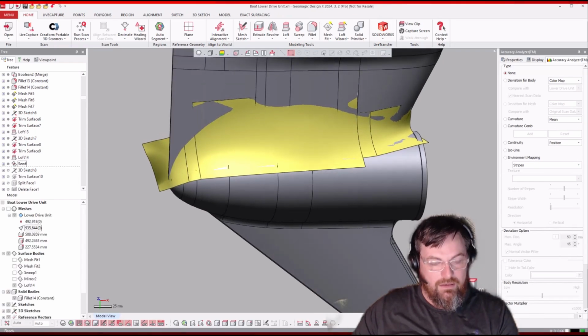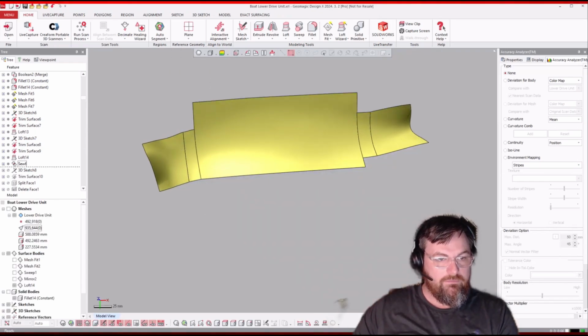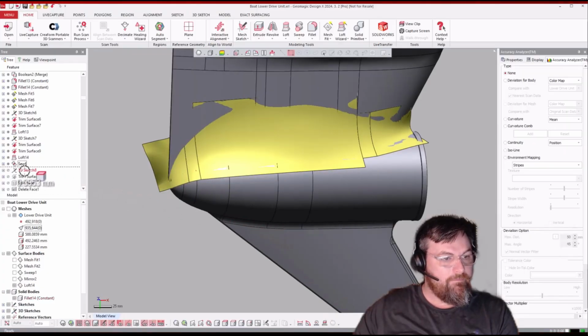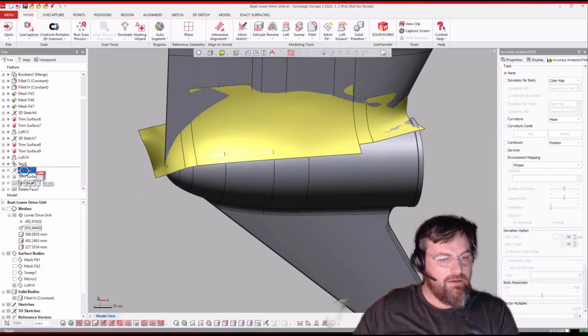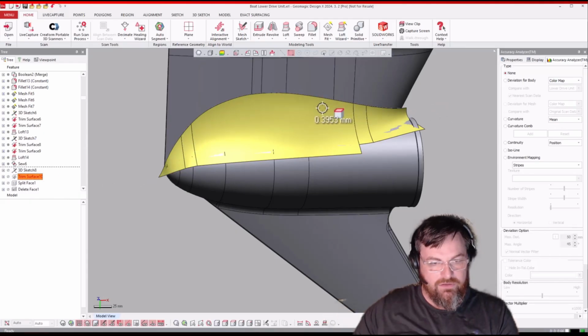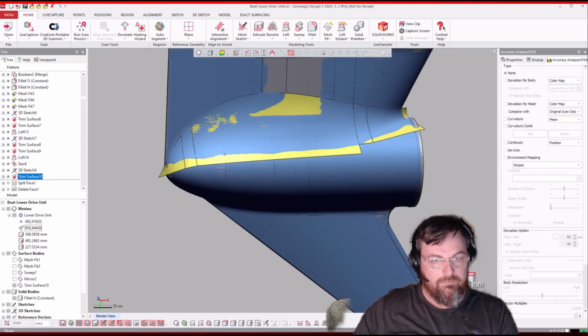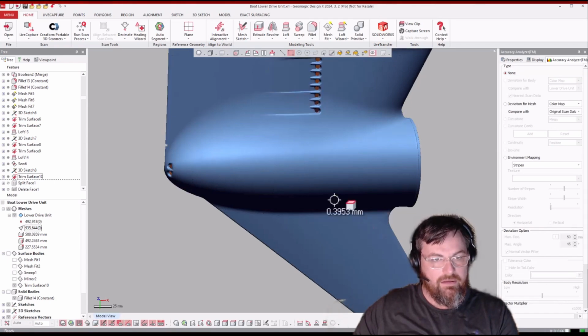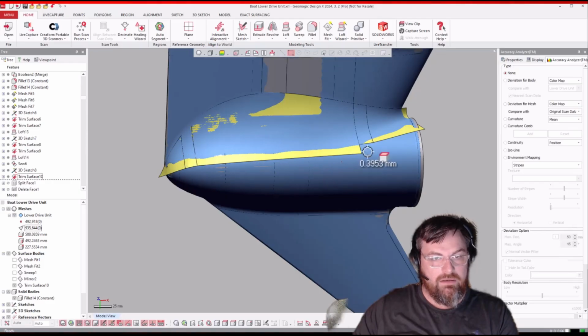So that's starting to look a lot better, where we got that nice surface draped over top. Now, they had a really creative way of going about this. They look at that top surface that we just created, and they took a 3D sketch and trimmed it back with that nice flowing shape that the polygon has. If I come in here with the polygon and turn off the CAD surface in solid, you see here there's this nice beautiful swoopy shape that we captured.